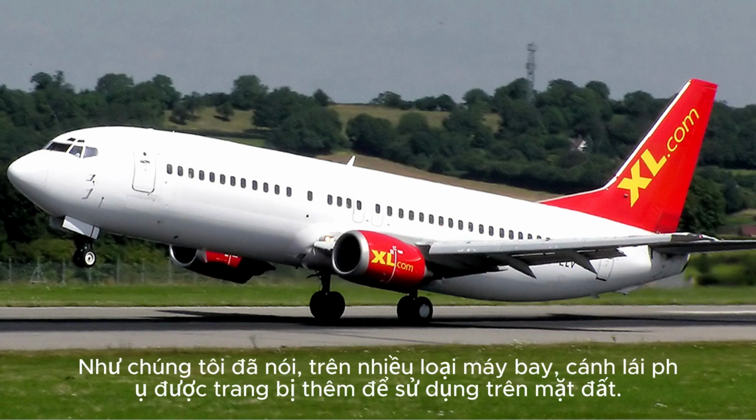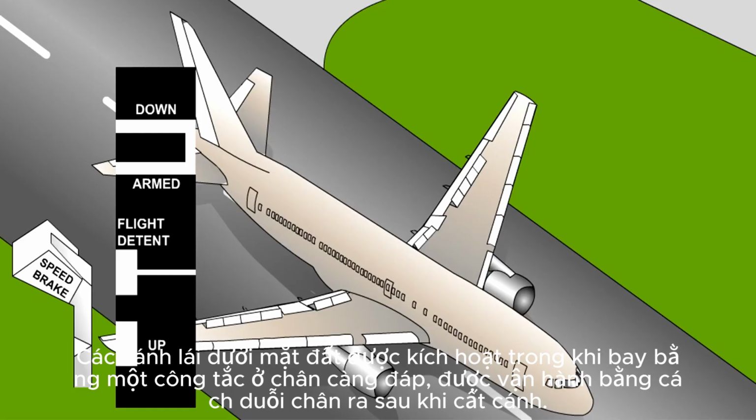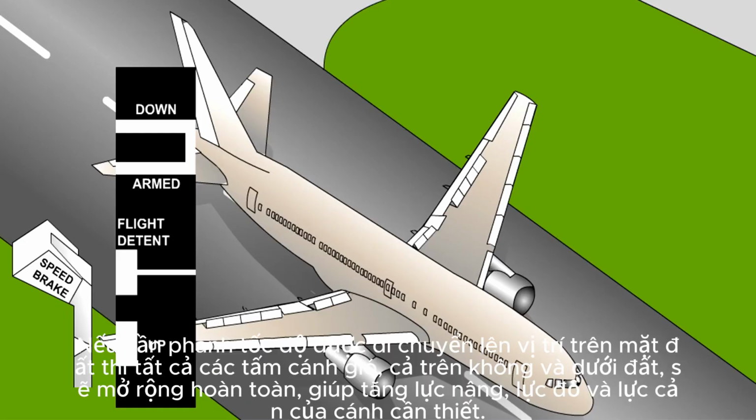As we have already said, on many aircraft types, additional spoilers are provided for use on the ground. The ground spoilers are made inoperative in flight by a switch on the undercarriage leg, which is operated by the extension of the leg after takeoff. If the speed brake lever is moved to the up position on the ground, then all spoiler panels, both flight and ground, will extend fully, giving the required wing lift dump and drag increase.